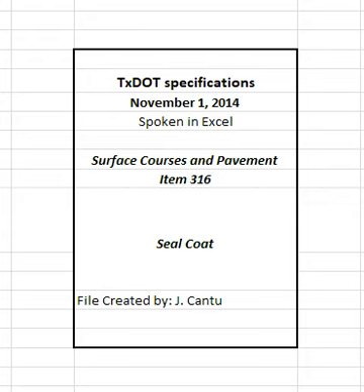5.1.2 Weight. Asphalt material will be measured in tons using certified scales meeting the requirements of item 520, weighing and measuring equipment, unless otherwise approved. The transporting truck must have a seal attached to the draining device and other openings. Random checking on public scales at the contractor's expense may be required to verify weight accuracy.